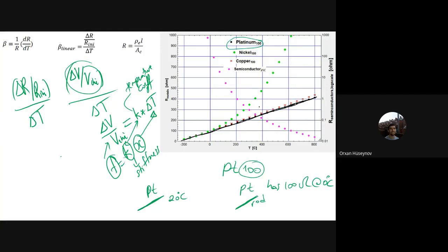Okay, good. This is the PT100, and this is the resistance of the PT100 in ohms. You can see the ohm, and this is the temperature change. I increase the temperature; at 0 degrees Celsius, it will have 100 ohms. Approximately 100. So sorry, it is not at 0 degrees Celsius. That is the error that I am having.